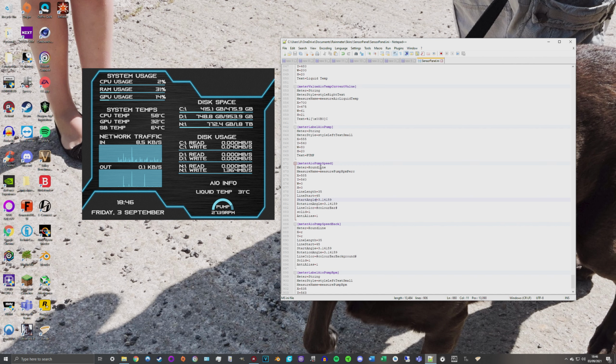Now, rotation angle also uses the radians value, as previously mentioned in the start angle explanation. This option here is also very important, as it controls the size of the angle of rotation for the meter, which easily enough is going to be pi again. So that's the value of 180 degrees in radians.